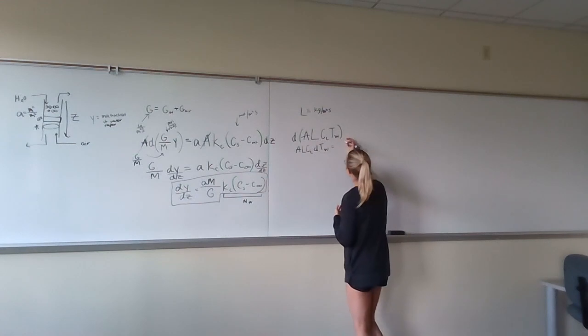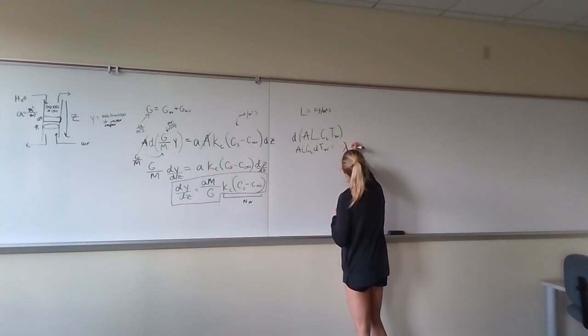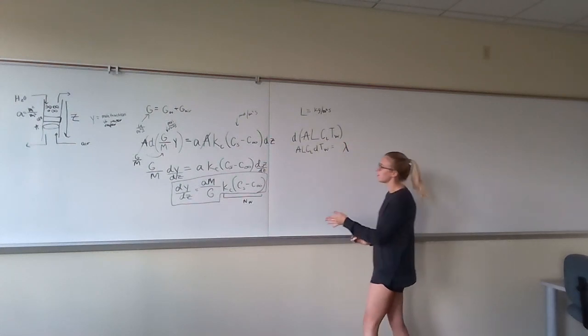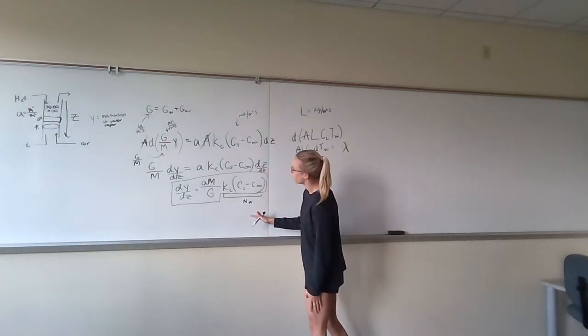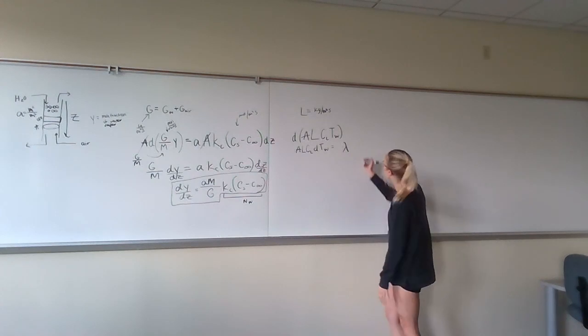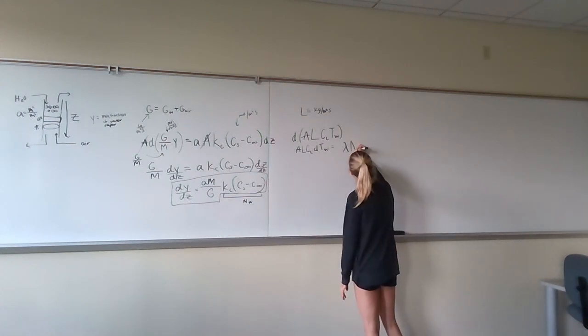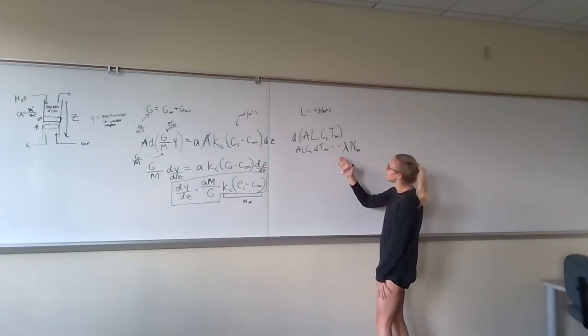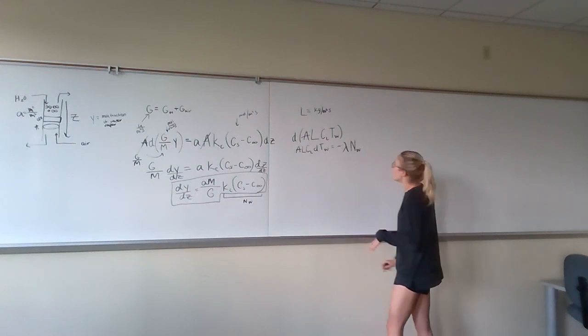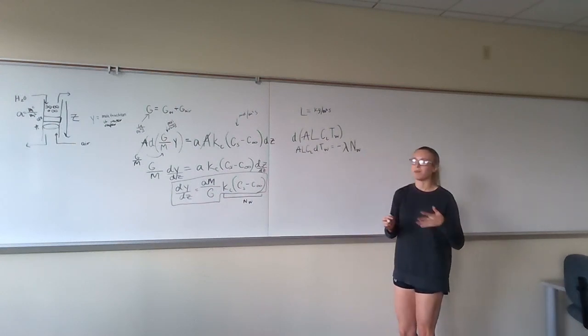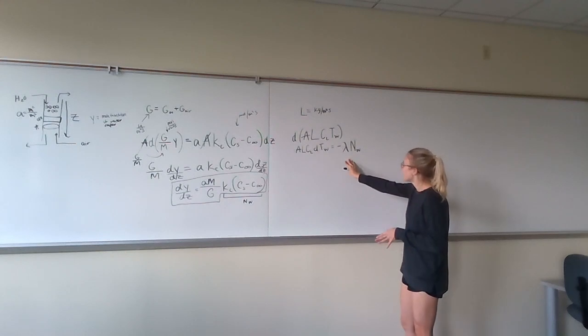So first of all, we have the heat of vaporization, and I'm going to multiply this by the molar flux of water, which we've already defined over here when solving for the change in mole fraction. And then we'll also make this negative because as the water is evaporating into the gas phase, the temperature of the water is decreasing. So the evaporation will cause the temperature to decrease, so this value should be negative.